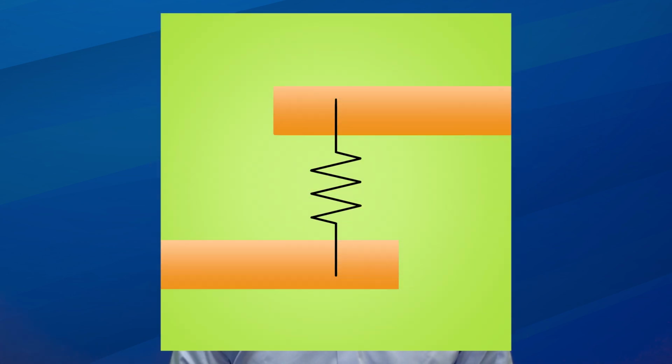Now, there isn't actually a resistor present, but the concept is that the space between the traces, which could be FR4, air, or even residues on the surface, can act to transfer current across those patterns, in essence, an effective resistor. In reality, what our meter is measuring is the current that is flowing across the gap and using Ohm's law to convert that to a resistance.